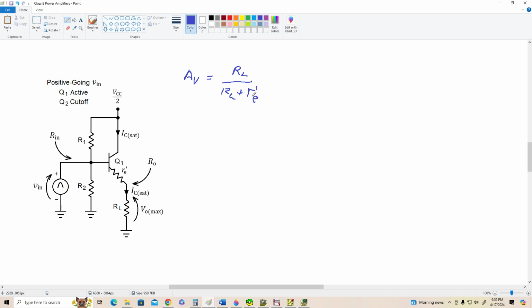All right, let's look at the input resistance. Now our source is looking at the biasing resistors. I'm ignoring the diodes for right now, but we're going to see R2 in parallel with R1 going to ground through VCC. Now, there's a little bit of ambiguity here, let's call it, because R2 is not going to appear in the circuit for all of the input, but part of it, okay? So I'm just going to include both of the resistors in this calculation, because it's a little bit on the conservative side.